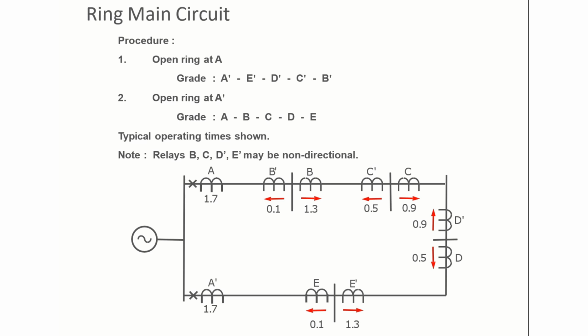Remember again, we are explaining this concept of directional relay on the basis of CT only to understand the concept. We will discuss in detail how to determine these directions using the concept of polarization quantity, MTA, RCA, ROC in the upcoming one or two sessions. Then it will be very, very clear. Right now, the concept is that we should trip only those sections in which the current direction is in the same direction as we have assumed during our setting.